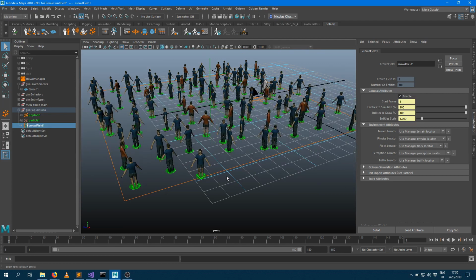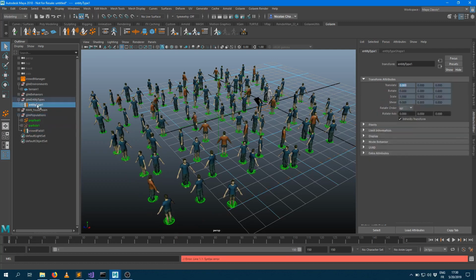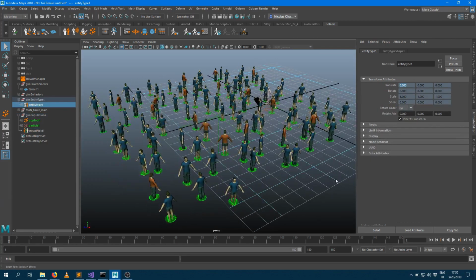So what you see here is just one node being displayed. It's that node there, and what you see here is not actual Maya geometry. It's not really possible to have interactive Maya when you got thousands of characters. So we have our own way to draw geometry, which is handled, for each type, by its node. So every time you create new characters, the display of those characters will be handled by that node here. So all you see here is some GPU geometry, and everything you see in the viewport is what you will get at rendering time.